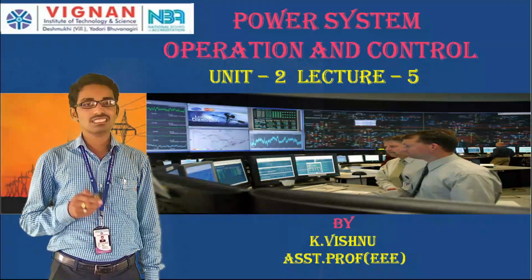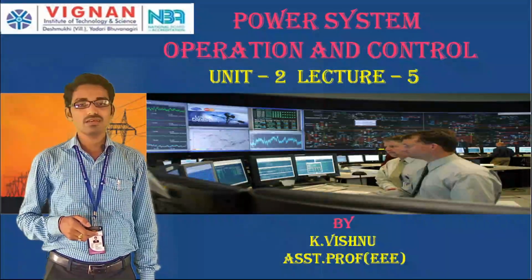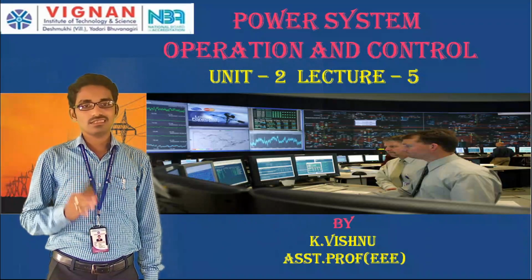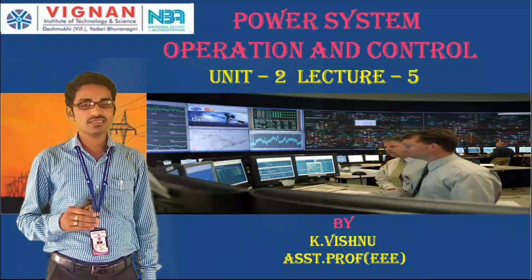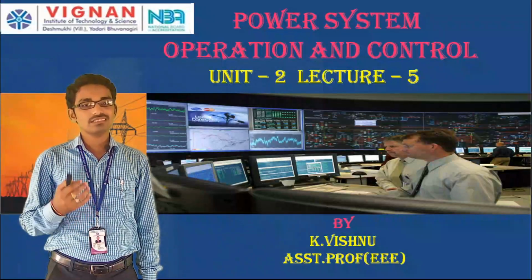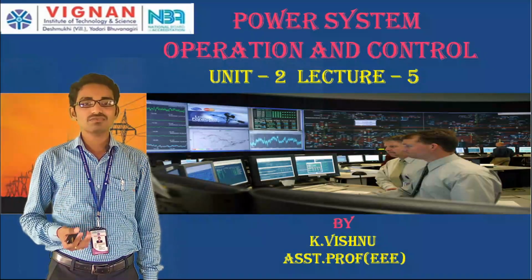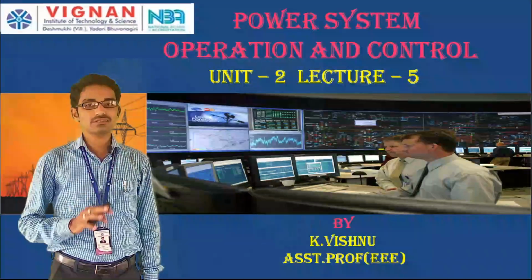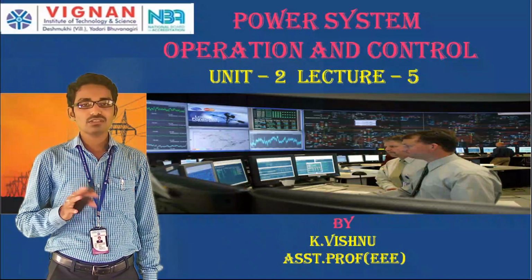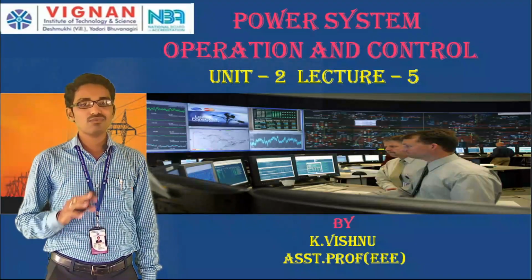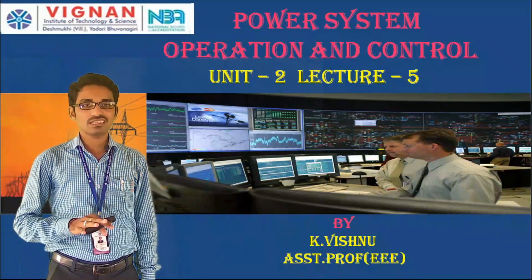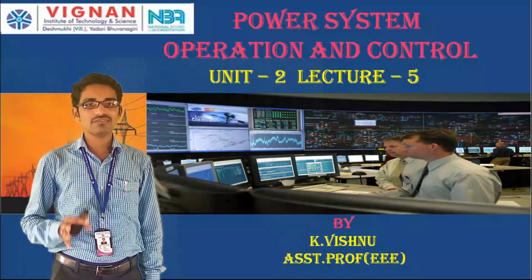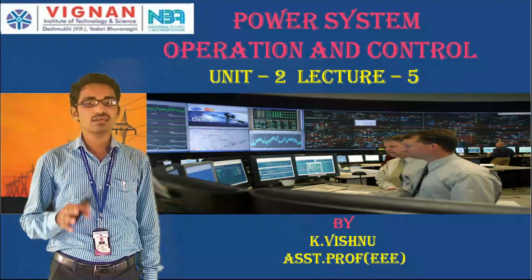In the last class, we saw the synchronous phase modifier. Why is it given that name? Because a synchronous phase modifier can be used as a shunt reactor as well as a shunt capacitor. A shunt reactor absorbs reactive power, and a shunt capacitor injects reactive power into the line. So we have two devices in one single device: a shunt capacitor and a shunt reactor, incorporated in a single device called a synchronous motor, which is operated under no load.